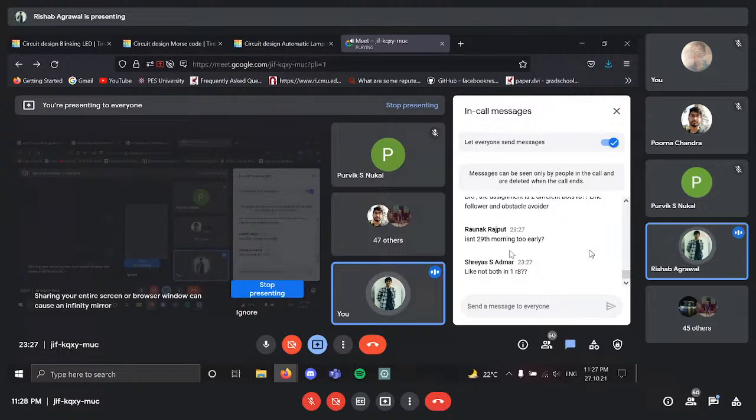So you just use an ultrasonic sensor and it is going to follow the line the way it was. Everything remains the same. The only difference is that there has to be one extra condition, saying that if there is an obstacle that the ultrasonic sensor senses, then the speed of the motor should become 0. It should not be relevant with what the LDRs are sensing anymore. Because if there's an obstacle, then the program should just stop. So there doesn't have to be anything more complicated like trying to navigate around the obstacle. That is not something you guys have to worry about.